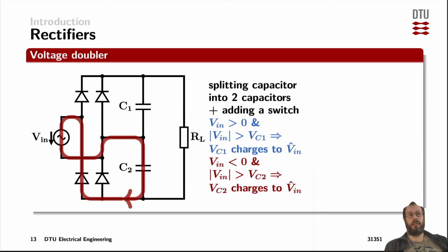And with the negative half wave, we would only forward bias the lower left side diode here and only charge the lower capacitor here. Note that the upper one is still charged from the positive cycle of the mains, so we still get around 155 volts on the upper capacitor. And then we are doing the same thing with the lower one, so we are adding 2 times the 155 volts in the US example.